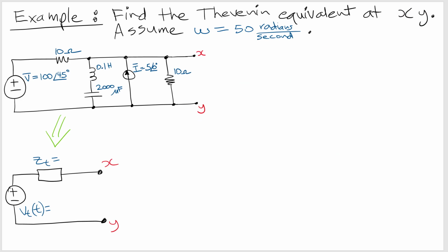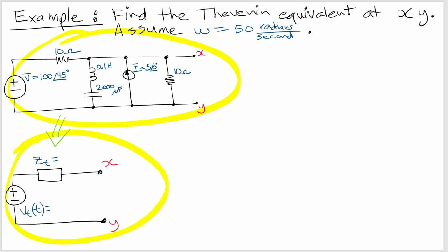So now, recall, when we're doing the Thevenin equivalent, we're transforming the circuit into its equivalent down here. So what stays constant are these points here, x and y. So there's 2 points, okay? That's how we can make a Thevenin equivalent. So then the circuit is equivalent at these 2 points. So no matter what you connect at these 2 points, whether you connect another circuit or make a measurement or whatnot, these two will be the same, okay?